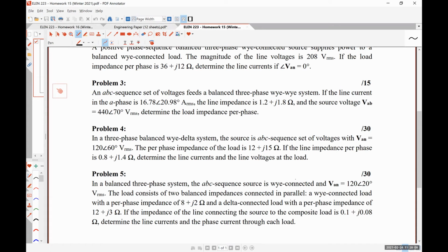For the first building, it'll be between the A and B terminals of the feed. For the second building, it'll be between the B and C. And for the third building, it'll be between the C and the A, so that for every 3 buildings, it's completely balanced. There might be a little bit of imbalance if the number of buildings isn't divisible by 3, but overall, it's fairly close to balanced, right?